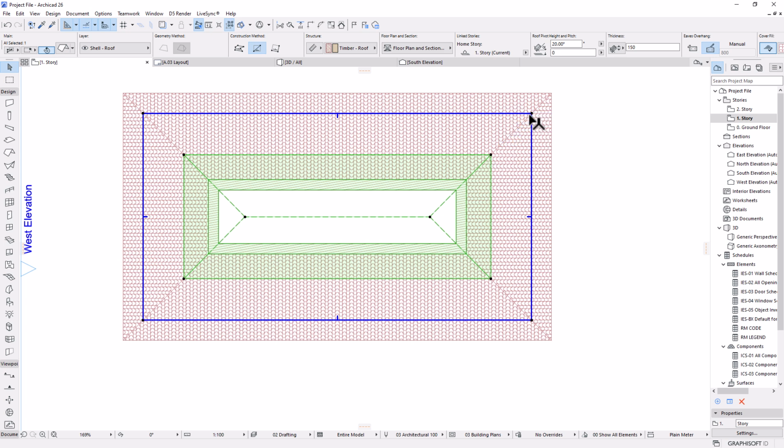Perfect. I would also need to do it for the reference line, but I would rather leave it in the same position as the main roof. Once we're done with that, I need to subtract this roof from the main roof because we have 2 separate segments. So this is going to be at a different degree. Let's come here under the roof pivot height and pitch and set this to be 40. The first one is on 20 degrees. This one is going to be on 40.